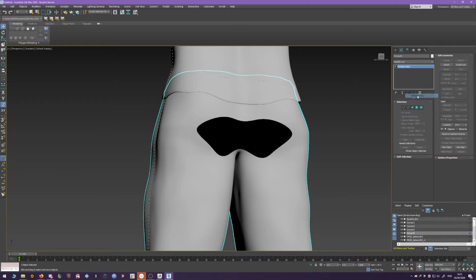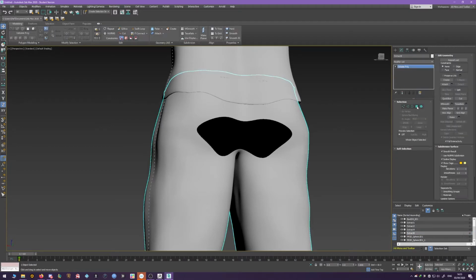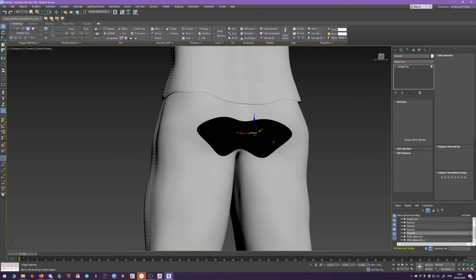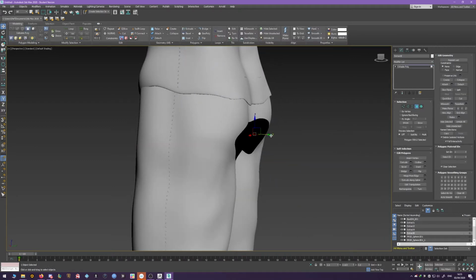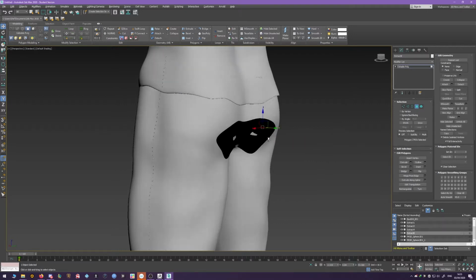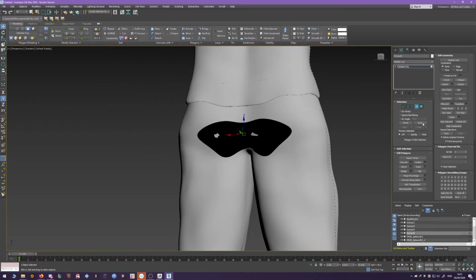So as I've said before, just select the subtool which has the issue, turn it into an editable poly, select polygon, and pick one of the black polys. Now from here, you can highlight them easily, and if you delete one, you can see what the problem is. So if you select one of the black polys, you can just select the grow button and keep it growing.